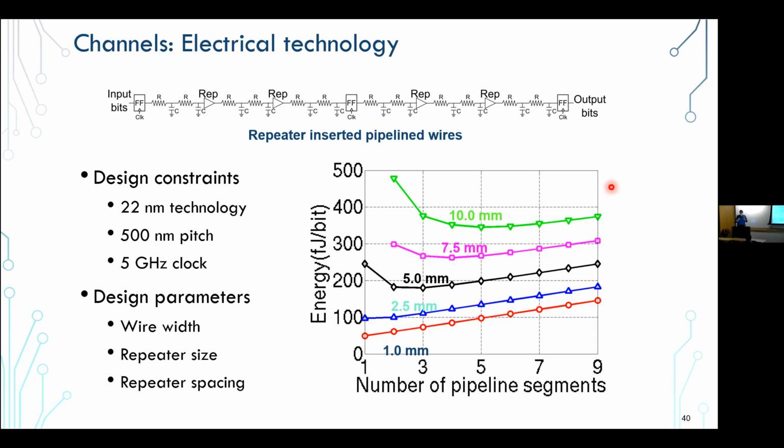Turns out if you're going these longer distances, you can't actually make it in a single cycle. If you just do a repeated wire, and you want to have a reasonable energy efficiency, so you have like a FO4 of 4, maybe 5, depending on what your target clock frequency is, then you may not end up traversing in a single cycle, and you don't want to necessarily do wave pipelining where you're just sending bits and they arrive 2 cycles later.